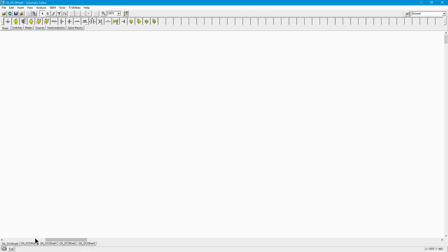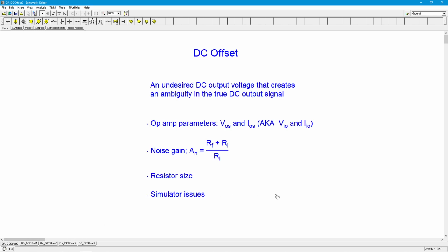Hello folks, it's Professor Fiore, and in this video we are going to be talking about DC offset in op amps. What's a DC offset? Well, basically it's a DC output voltage, an undesired DC signal, and this will create an ambiguity, in other words, an uncertainty in the true DC output signal. So if you were measuring a DC signal from a sensor, and you get an output voltage, and just to throw a number out, let's say it's 100 millivolts, a portion of that is not really from the signal, it's really a DC offset created by the op amp itself.